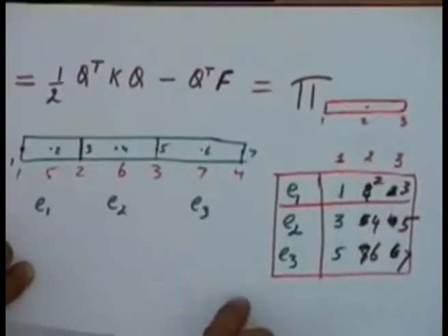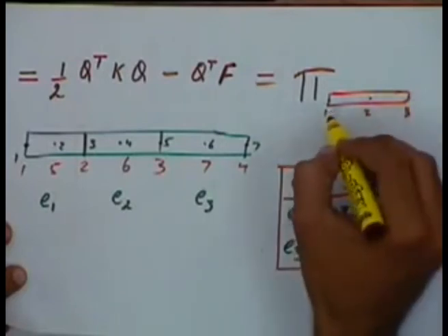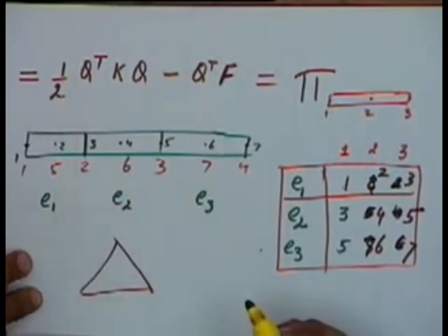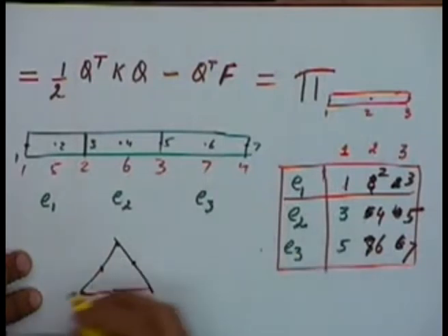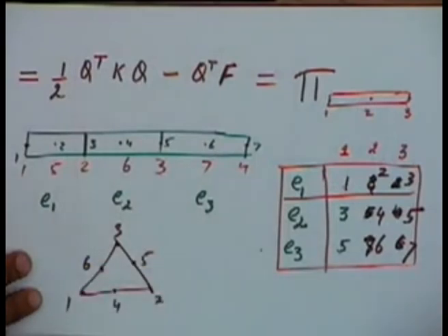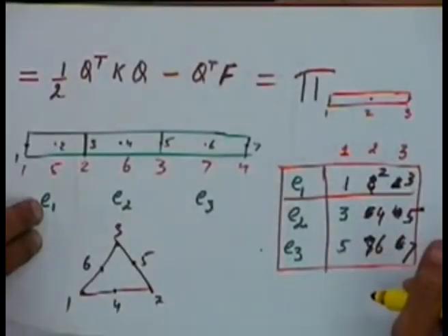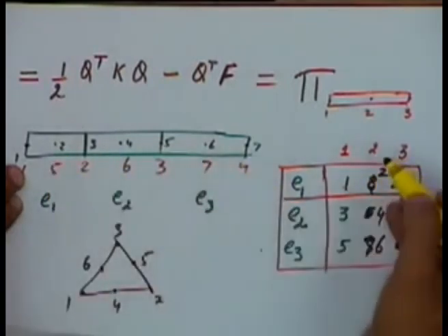But what happens is, this quadratic element that we have taken right now is only for a one dimensional element. Later on we will see if we have a triangular element, even there we will take a 6 noded triangular element, and there also we will do numbering like this. I don't see any specific advantage that you will gain from this numbering, because eventually you can always change your global numbering to suit this particular pattern.